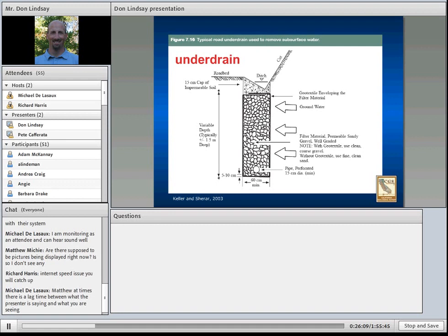Problems I have seen with these drains is the top of the drain is constructed too close to the bottom of the ditch, right in this area, causing the drain to be damaged when the ditch is maintained. And drain rock is placed all the way to the surface instead of using a low permeable soil cap, which causes the drain to be adversely impacted by surface flows.